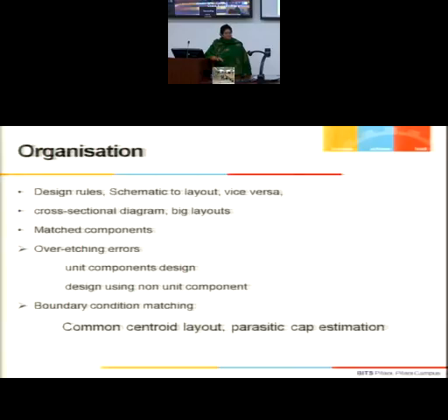So there is a window. Process variations have to be taken care of. Normally they are taken care of at the layout level, because there you use certain techniques in order to lessen the parasitic capacitances, in order to get near constancy in the drive current.